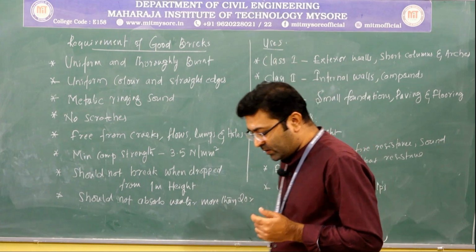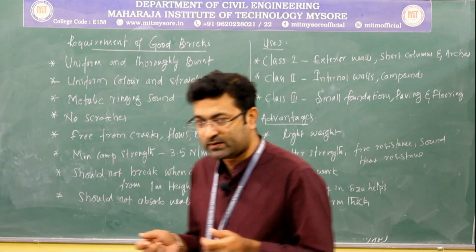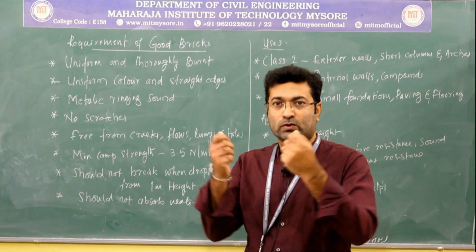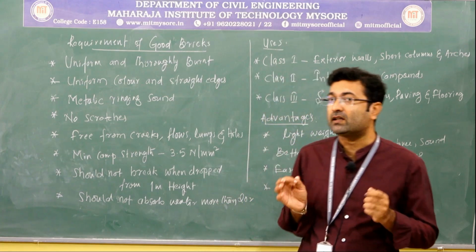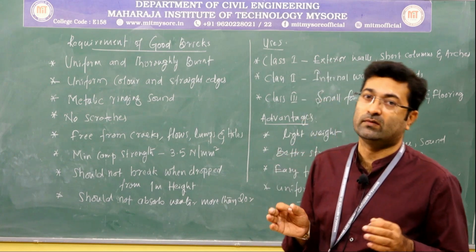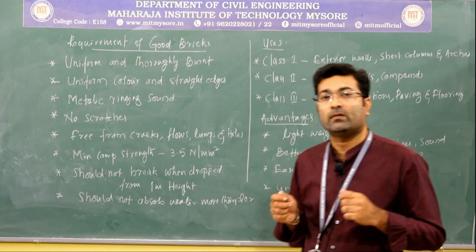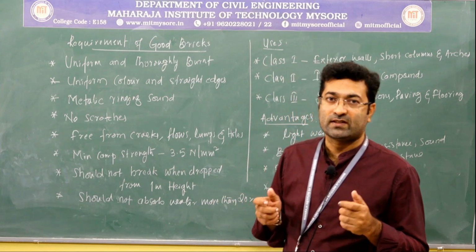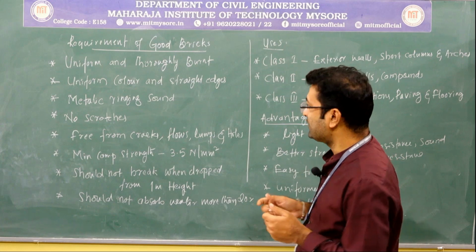Whenever we are purchasing bricks, during the checking of quality, if you strike two bricks against each other, we should be able to hear a clear ringing sound, which represents the quality of the bricks. If you hear a clear ringing sound, then we can assume that the burning process has been done in a good way and the bricks have attained a good strength.